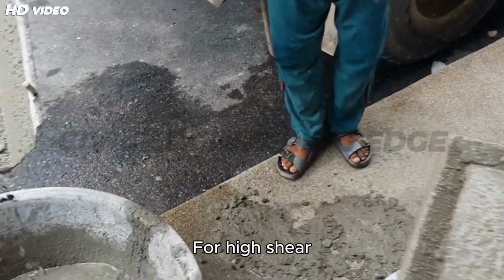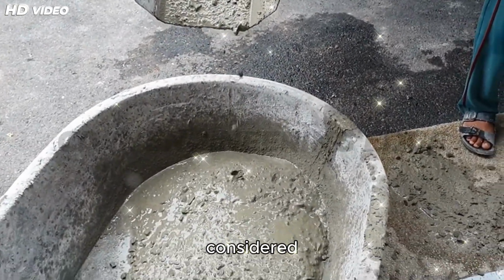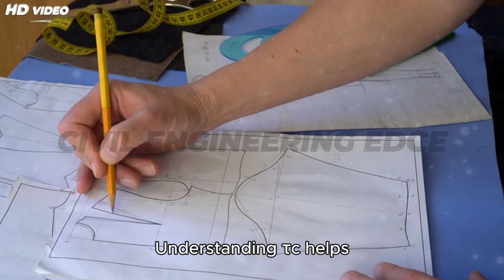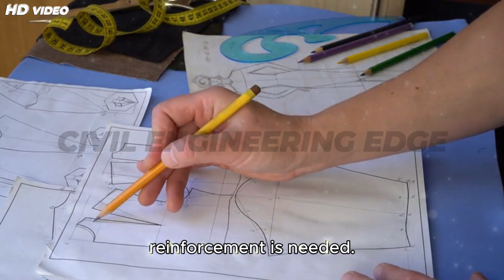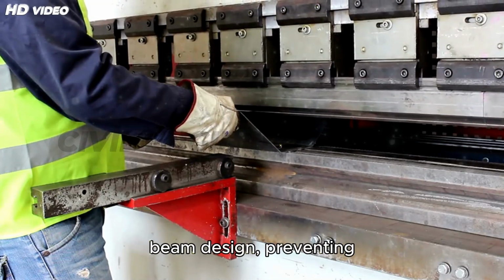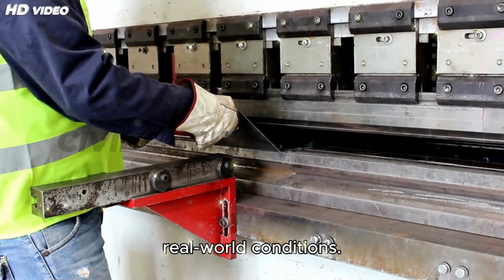For high shear stresses, tau v greater than tau c max, concrete is considered inadequate and redesign is necessary. Understanding tau c helps the designer decide whether concrete alone can resist shear or if reinforcement is needed. It ensures safe, economical, and durable beam design, preventing brittle shear failures in real-world conditions.